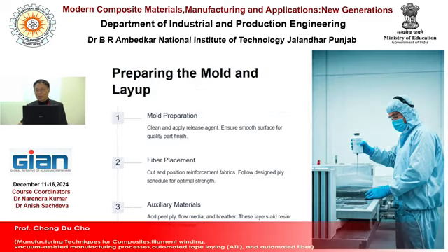Release agent is needed so that after curing finishes, the part can be easily ejected. So release agent is applied over the mold to ensure a smooth surface for quality part finish, because the mold surface condition decides the surface of the product.